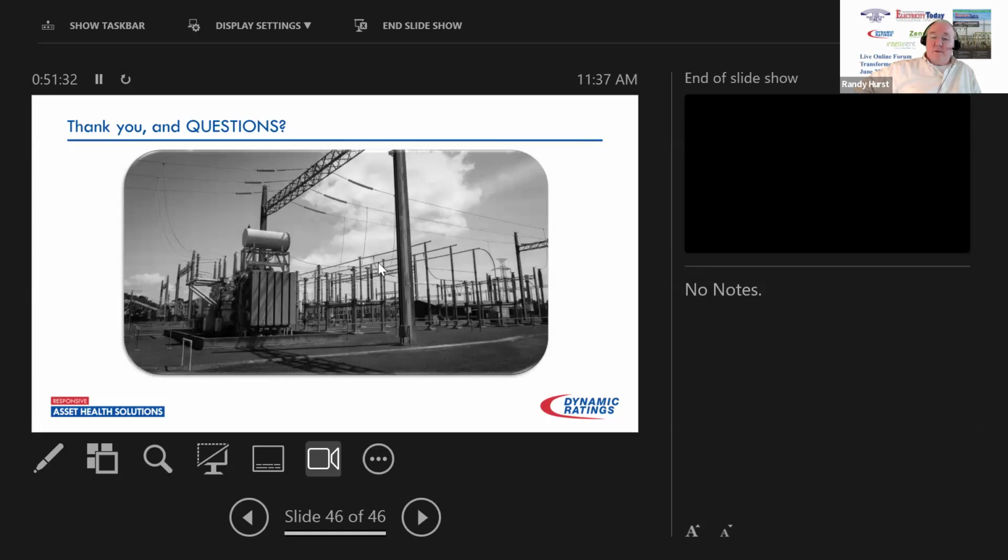First question: would you ever consider having a monitoring system take the transformer offline like a relay? My answer to that is no. And the answer from a lot of my peers is no. In the guides, you'll find the answer is no. It's there to wave the flag, so to speak, and start your research into why. You look at the data coming in. You have the data file, you have the archive of data, and you have to look at it from the point of view.